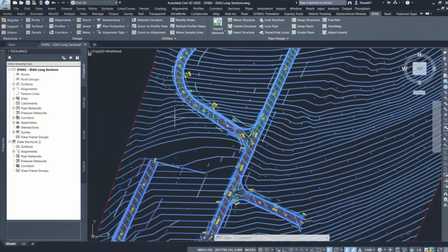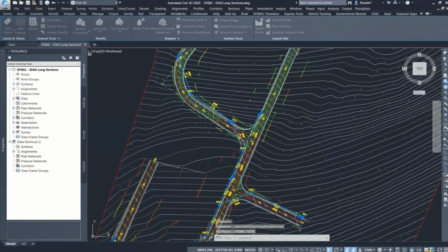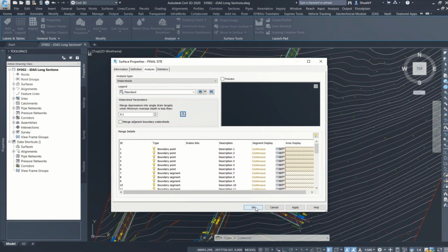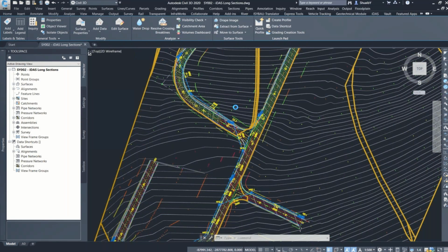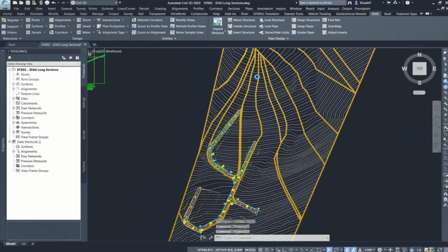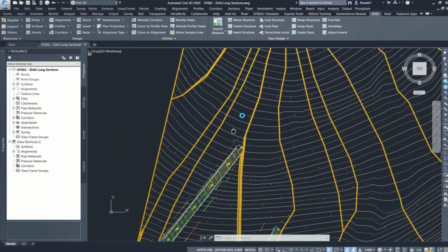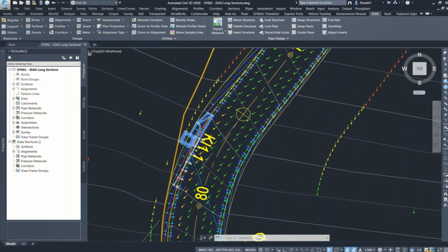Okay. You can see that there's tiny arrows on the actual surface, but what I'm going to do is run the watershed analysis again. Again, this was covered in part 1, but just a quick recap in case you forgot or you're a bit hazy. I'm just going to run the analysis very quickly. Okay, and you should see it gives you the crests now. Can you see that? Now, how awesome is that? You can actually see the drop or the potential flow of water depending on the actual elevation of the terrain. As you can see here, the water is going to be flowing down that way, it's going to be flowing down there. And these crests can actually help you to size your catchments.